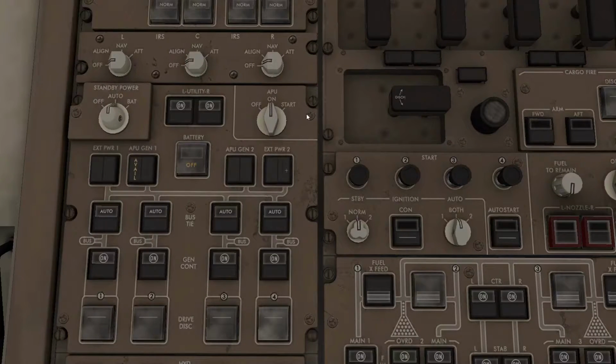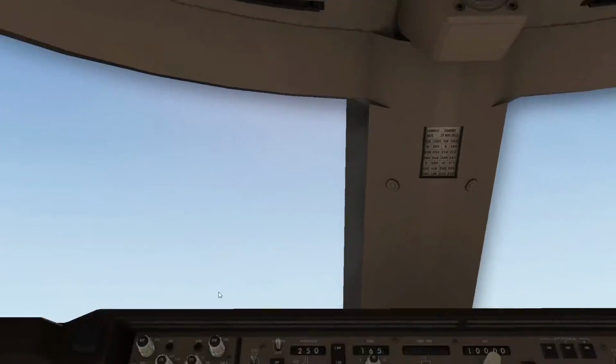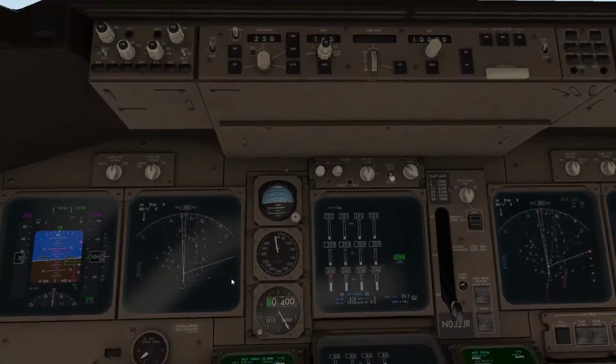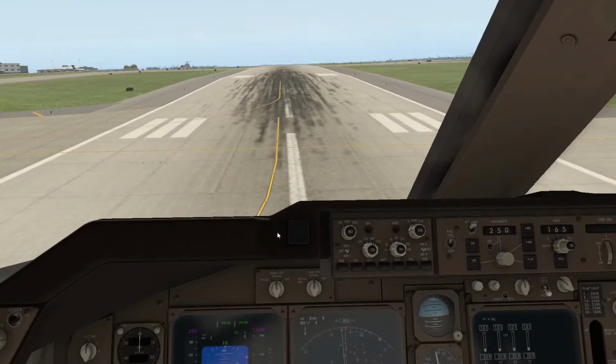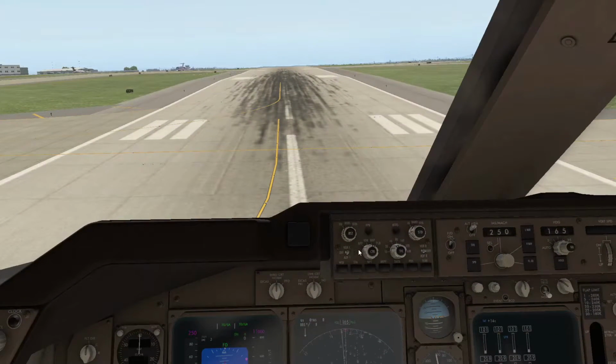Make sure whenever you are playing the game, or if you are flying with the actual aircraft, if all of the engines fail, you need to just open this cover and turn on the battery. So the battery, like we have batteries in our cars, same way the plane has sufficient battery to just drive the electrical equipments of the cockpit, and not everything.